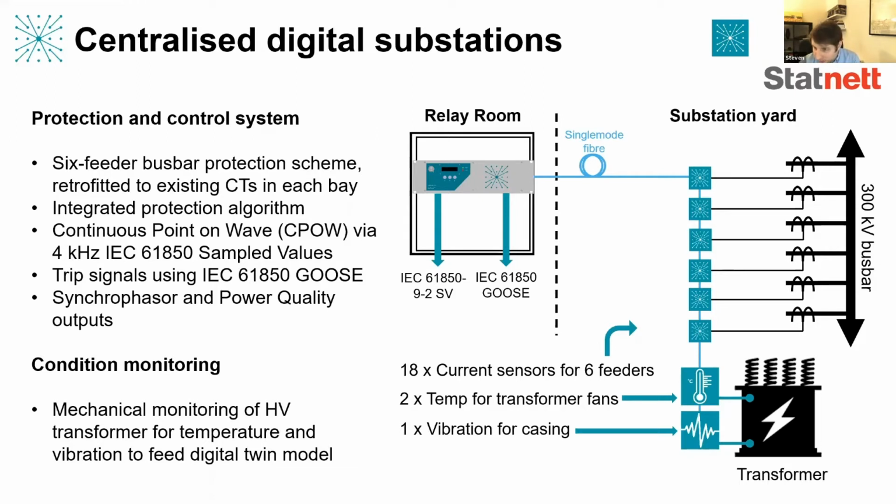And again, because this is a Synaptec system, I'll just emphasize again that this deployment is centered around a single optical fiber, which visits the CTs and the other sensors out in the yard. So we don't need a power supply going there, it's just an optical fiber. And these are not merging units, these are completely passive units.